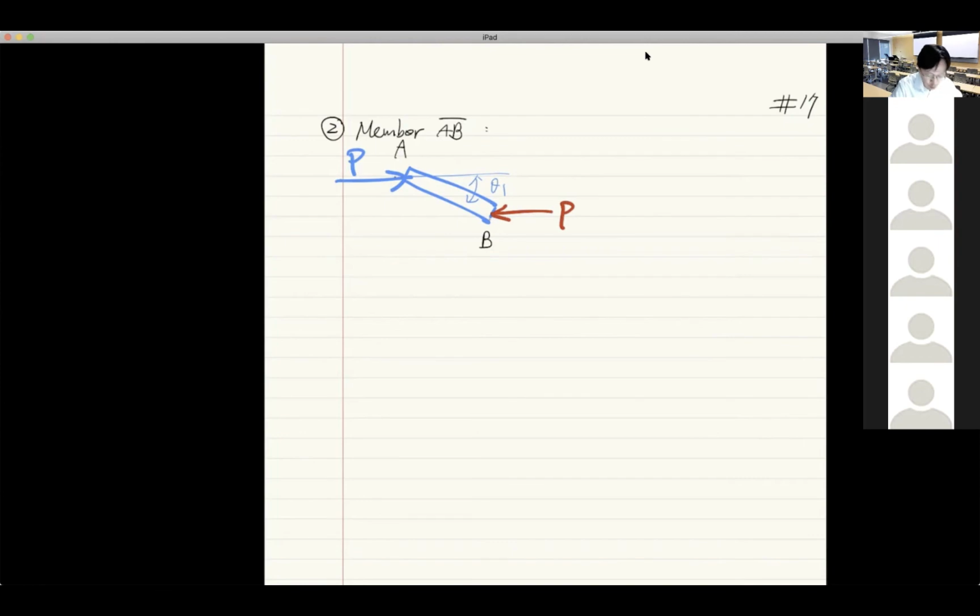Now, at point A, there's no bending moment. But at point B, because there's a rotational spring, there is an internal moment, right? Just imagine this. Before the deflection, this is our structure. You have a rotational spring like this. If you do not bend it, there's no internal moment. In this case, Ks will produce no moment.